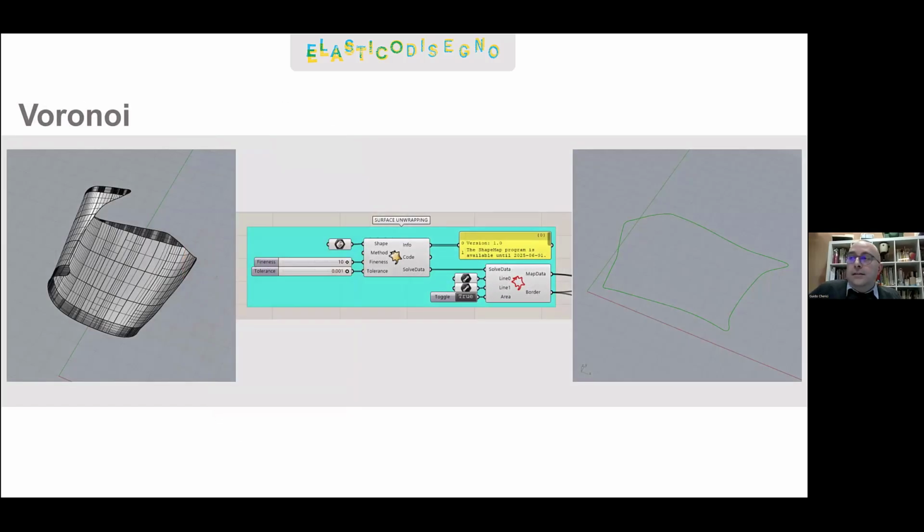And so for the next cover we used a Voronoi pattern, which doesn't provide enough protection for everyday use, but is widely used for industrial applications. In this case, we went back to the actual surfaces of the covers that we designed, and we created a surface that sits exactly in between the outer and the inner side of the cover. So while in the previous one we had a single surface, here this is a polysurface made of about 100 different little surfaces stitched together.